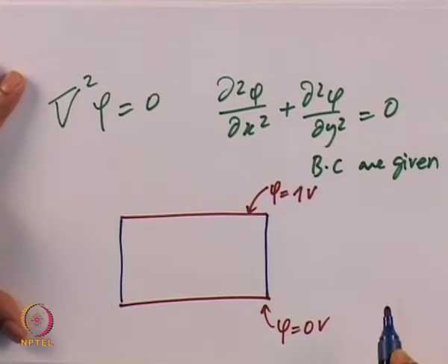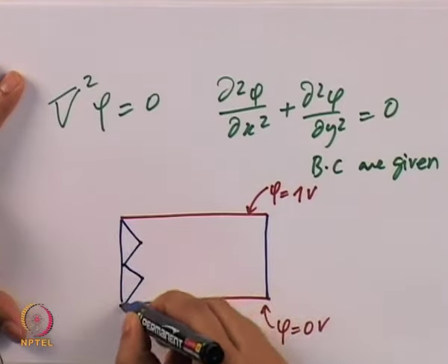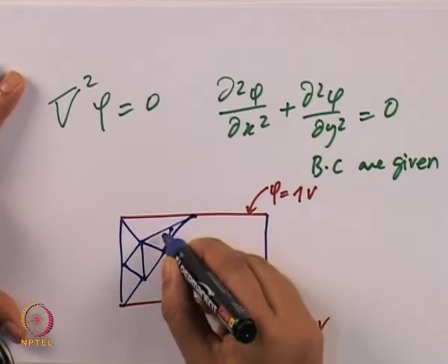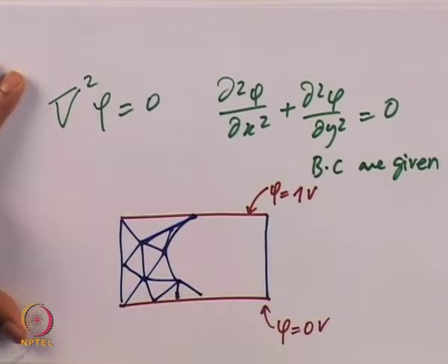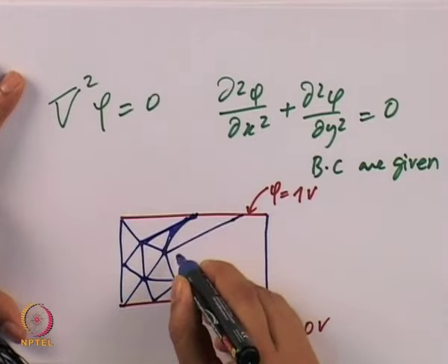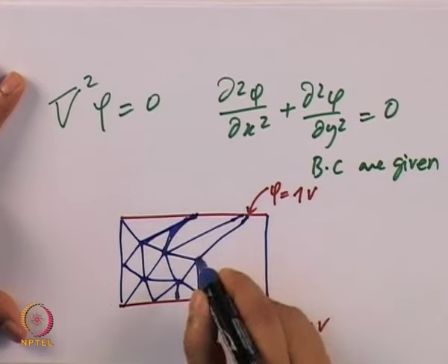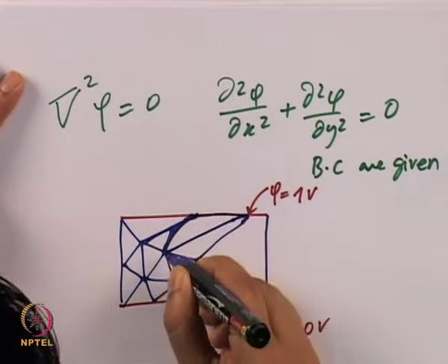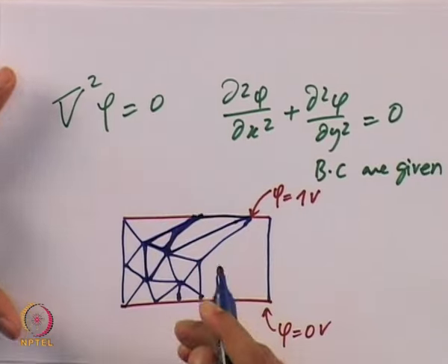So we are going to discretize it using triangular discretization. Let us look at how the triangular grid is going to look. For example, we are interested in using an unstructured grid. The grid is going to be very irregular. In some places you have very fine cells, in some places very coarse cells, and the cell size is going to depend on the gridding or meshing software, and this is one of the things we should be very careful about. For example, here you have a triangle that is very long on its sides, and there is another triangle which is symmetric with one or two sides, whereas the triangles in the middle are very fine.